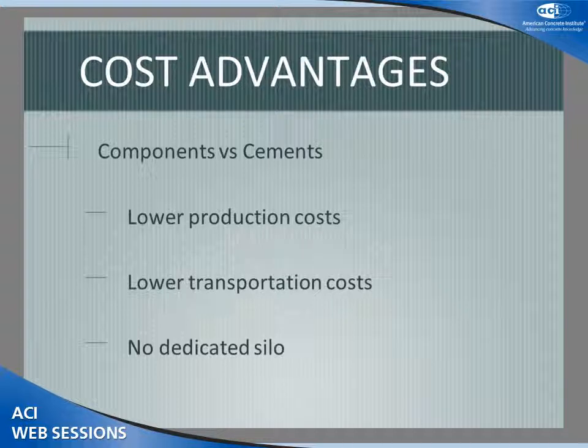Transportation costs for a Type G component are more economical than transportation for a Type K component, since the dosage rates for the Type K component are typically twice that of a Type G component. During construction of Type K projects, an additional laborer is typically employed to keep misting the concrete to avoid surface drying. The recommended 7-day water cure also requires additional resources added to the construction costs.